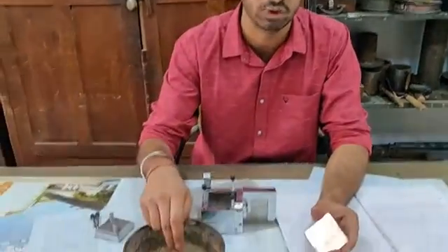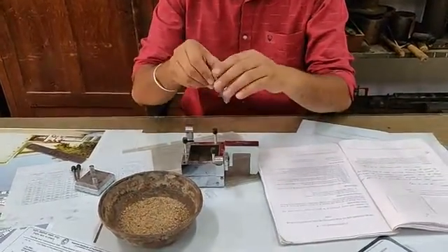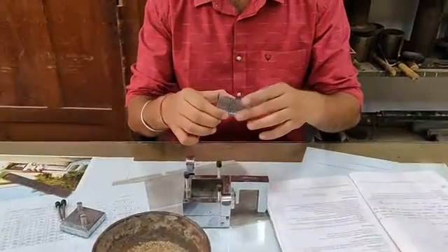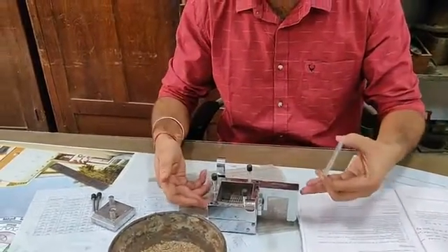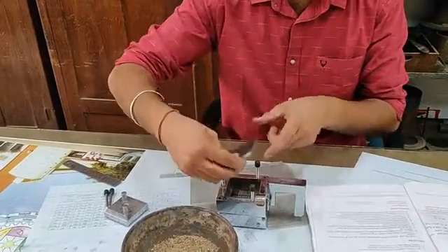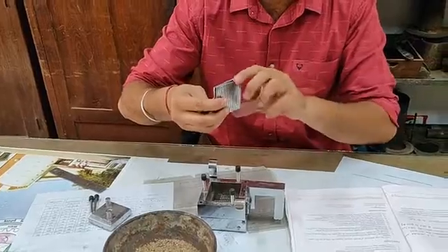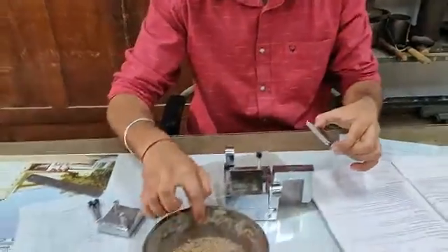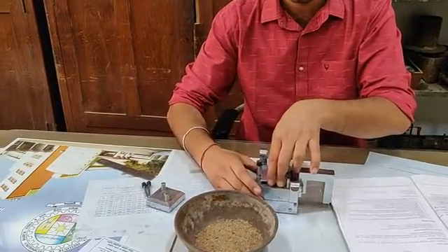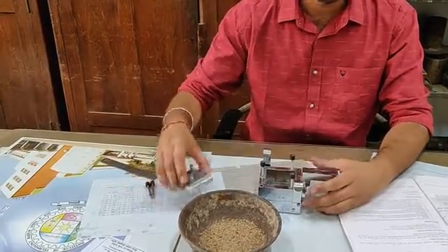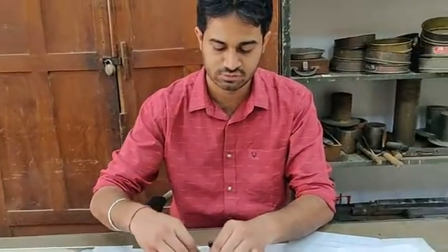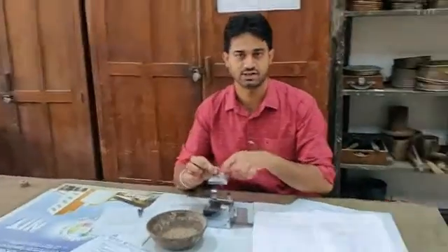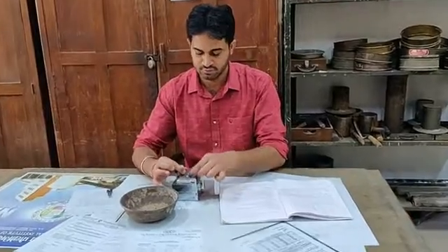When we fill this soil into the shear box apparatus, then on the top of it we place these two plates perpendicular to the loading direction. If the load is applied in this direction, then these plates are parallel, so we will put them in the perpendicular direction after filling the soil. Then on the top of it is the loading pan. We will place a ball here which provides the centric loading, and we will put this whole assembly into a box, and then perform our direct shear test.